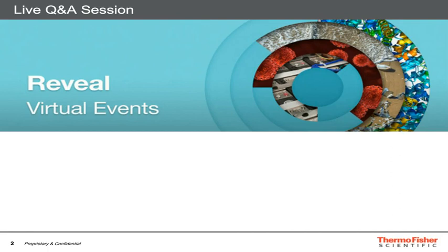I believe so. In terms of spatial, if you talk about cross-section, so if you have a multi-layer where you have micron layer thickness, you're generally better off with XPS using depth profiling. So sputter through the sample rather than cross-sectioning it and imaging it. If the layers are tens of microns thick, then yes, you could do a cross-section. Or if they are thinner than that, around hundreds of nanometers or microns, then